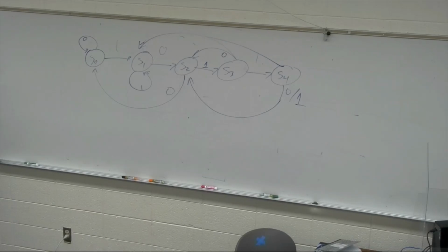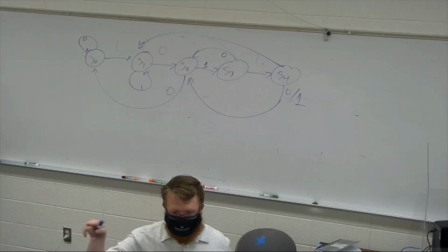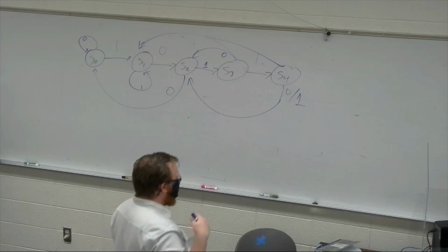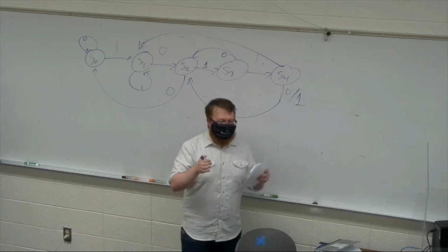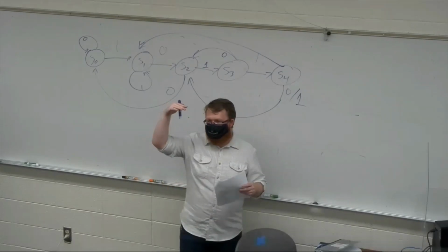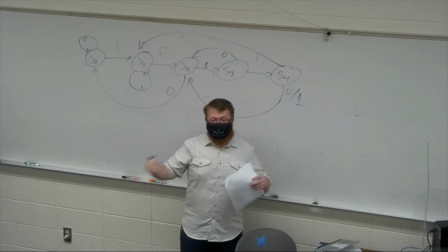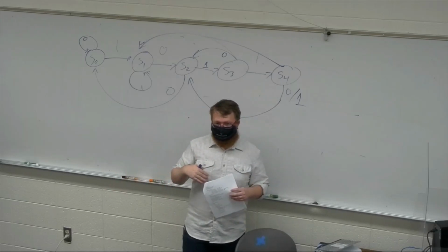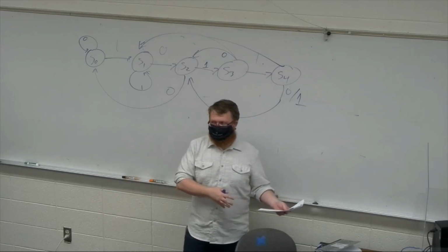Not clock and enable. So there's only one window of opportunity. There was one that barely meets the timing at the very beginning of it. That was okay, as long as you clocked it in right. So you look for possibilities, because X starts high and then it drops low, and it needs to go back high before we clock in any new data. If X doesn't change, the flip-flop output can't change, right?